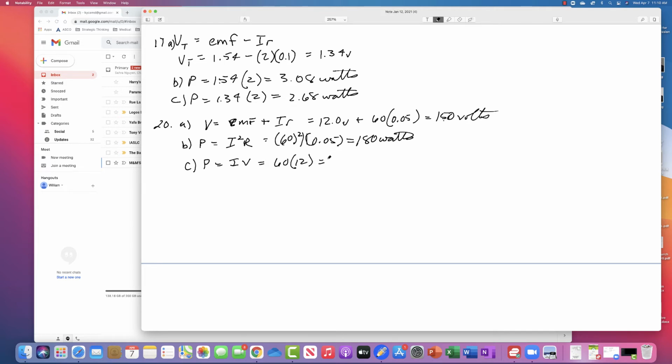And then you subtract from that the internal watts that are being dissipated by the battery, and so what's left is 540 watts. So this is the total power that's being supplied. 180 of it goes into the internal dissipation of the battery, and the rest goes to converting the battery's chemicals so that it can produce power in the future.